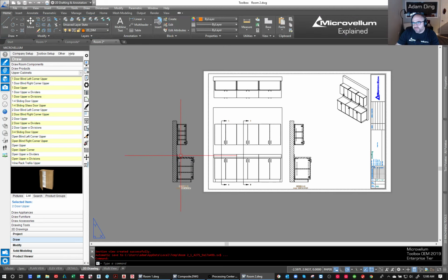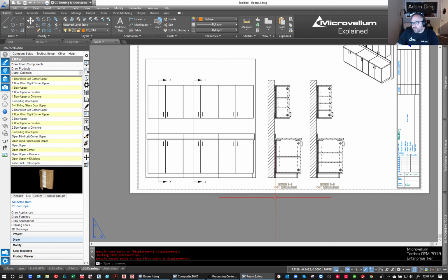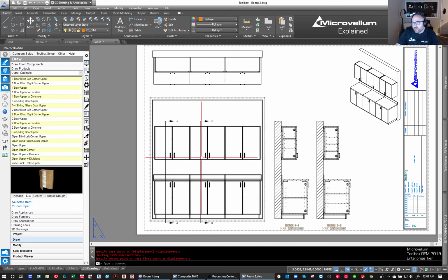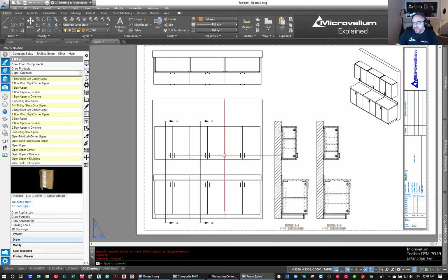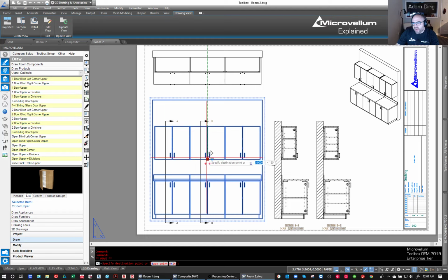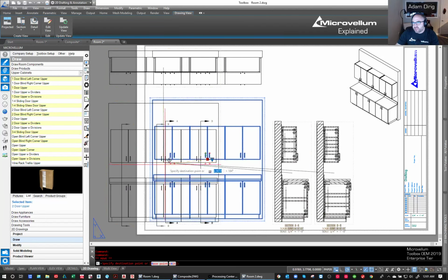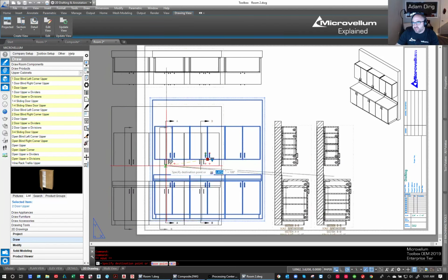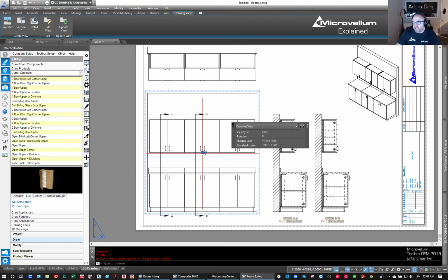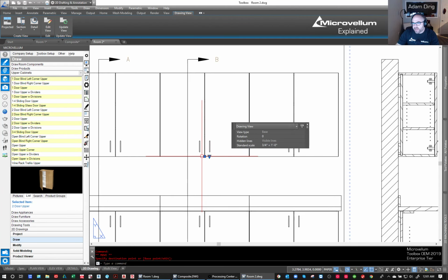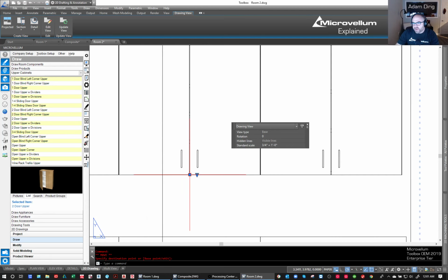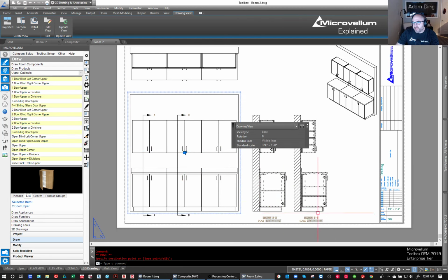And then once I've got it generated, I'm going to pull to the right. Move this to the right. Now these are a little close down here. So what you can do, and the benefit of this is I can grab this parent view and see how it all aligns. See how the sections and the plan view automatically align with what's happening to this elevation, even the section markers. It's all parametric with that. So I'm just going to move this around on the page to get it just the way I like it.